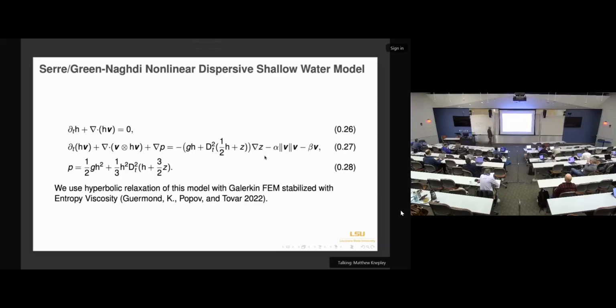Another one, you're probably familiar with the St. Venant equations or the shallow water equations. You can extend that to deal with non-hydrostatic pressure effects, but you can then push your vegetation into drag terms. So there's a quadratic and a linear drag term. So what we'd like to do is run the full three-dimensional Navier-Stokes model, actually representing the vegetation, run a series of experiments, and then derive these coefficients for these larger scale models.